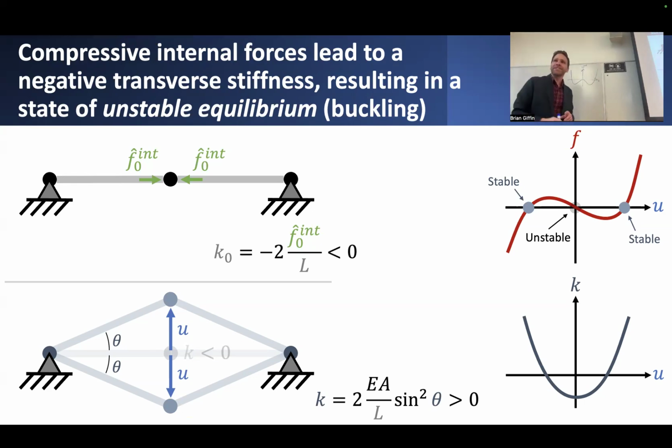And interestingly, the principle of minimum potential energy says that this system will be in equilibrium when we achieve minimum potential energy. If this is potential energy, minimum potential energy occurs either here or here, which is basically exactly where this S-shaped curve passes through the x-axis. But there's another point, another inflection point here. It's a local maximum, but it is nonetheless a location where the slope of the potential energy function is equal to 0.